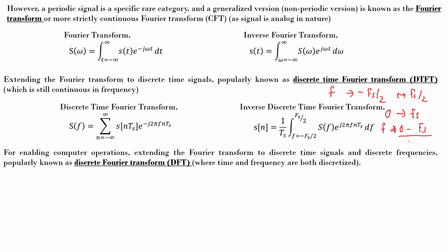But then the problem is, the moment you discretize the frequency, just as when we discretized the time, we found that the spectrum is replicating, similar to that, your time also will get replicated. That means whatever is the duration of this time, outside that it seems to be replicated. That is because whatever you do in time, it is dual in frequency, which I told many times, right? So when you discretize in frequency, the time will also get replicated. That is a very fundamental point.